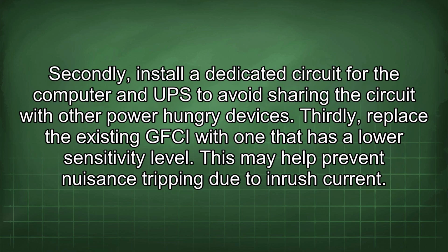Secondly, install a dedicated circuit for the computer and UPS to avoid sharing the circuit with other power-hungry devices. Thirdly, replace the existing GFCI with one that has a lower sensitivity level. This may help prevent nuisance tripping due to inrush current.